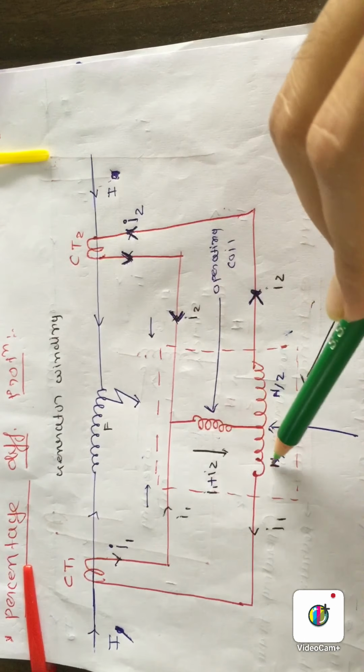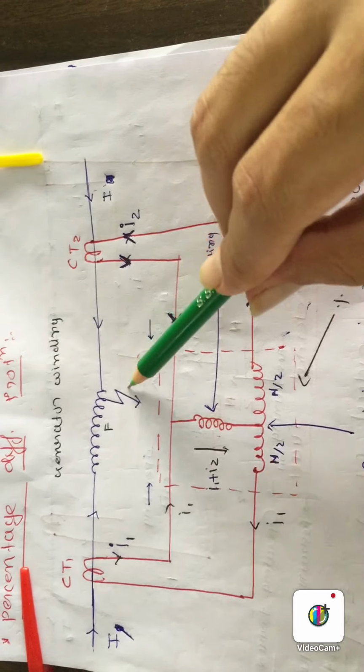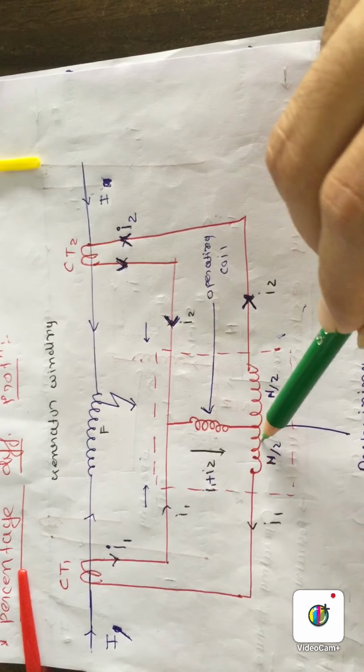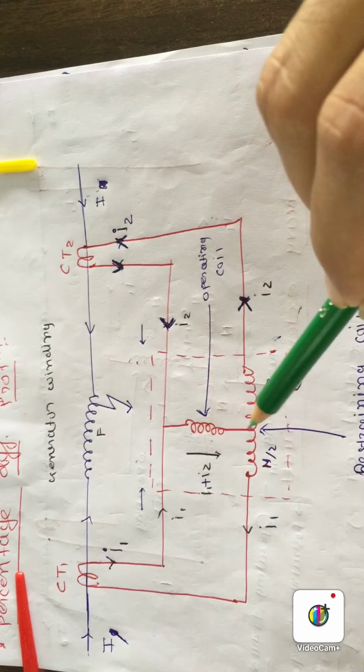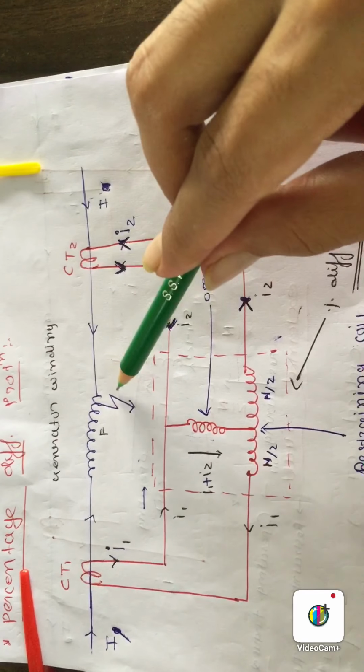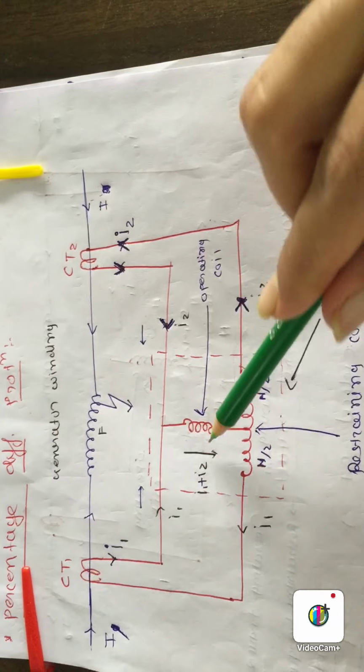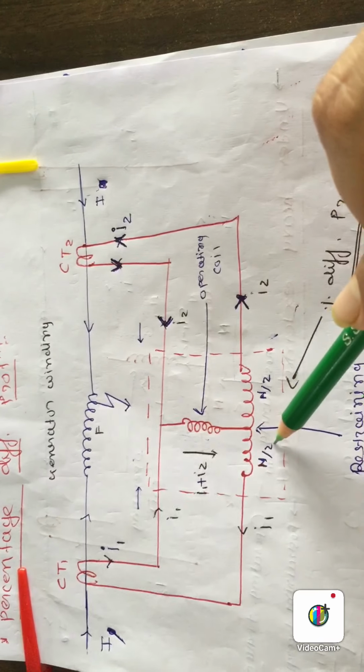So you know that always in faulty condition the retaining torque will not become zero, but for a fault available on the internal side, the operating torque will become greater than the retaining torque.